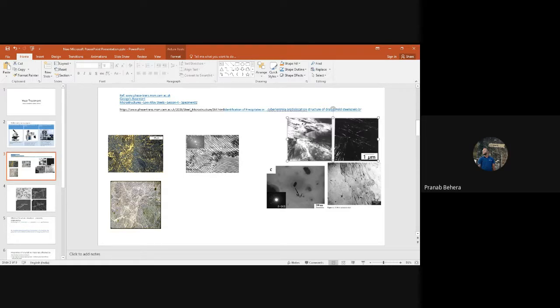Okay, this is a lath of martensite, and this is a bright field image. This is a dark field image. Anyway, these are precipitates. You can say M23C6 precipitate. This is a precipitate of chromium, iron, molybdenum basically. These are of nano size. As I told, I've shown you some figures. You can see them using TEM carefully. And these are dislocations. Dislocations are also very fine, but still you can see them by using TEM. Okay, fine. You got the things.